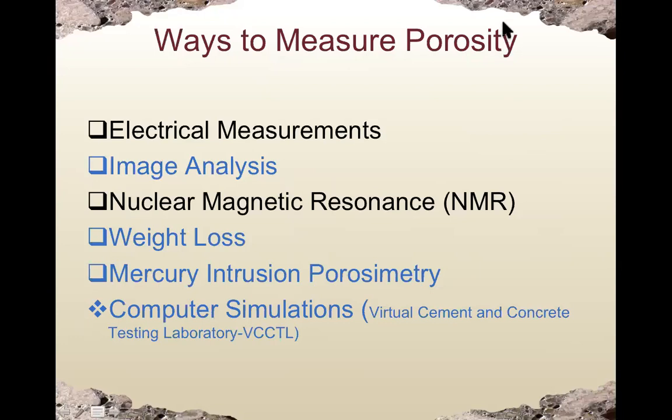Okay, then let's talk about another topic, how we can measure the porosity. So we know porosity is very important, controlling the strength and also the durability of concrete. But how we can measure that? There's many ways to do that. From electrical measurements, measure the electrical resistance of concrete. We can take a picture and study the image. Okay. We could have some other methods such as NMR, or weight loss, or mercury intrusion porosimetry, or even computer